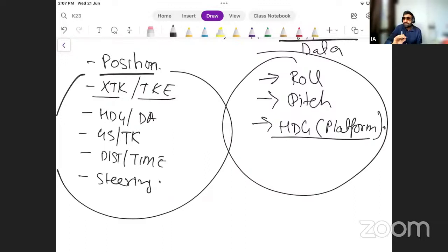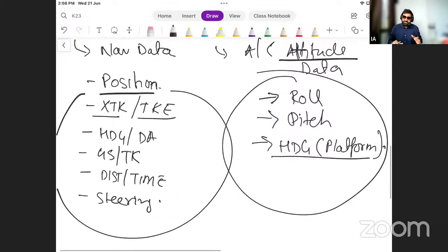A very important point, very common point. And these rate gyros are single degree, or 1 degree of freedom, gyros. So now in an INS, which is the older version, we have 3 accelerometers. Mainly 2 are enough, but 3 accelerometers, including a vertical acceleration based one, can also be used. And then we have mechanical gyros, which have viscous fluid instead of spring, single degree of freedom. Rate gyros are the gyros. So we have 3 gyros, which will stabilize the platform, while we'll have accelerometers on the platform, which will give us all the data as mentioned here on the screen.